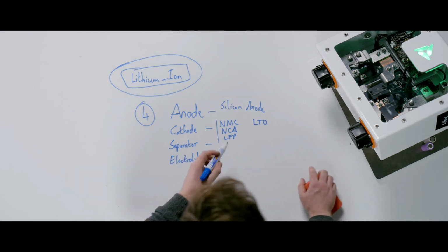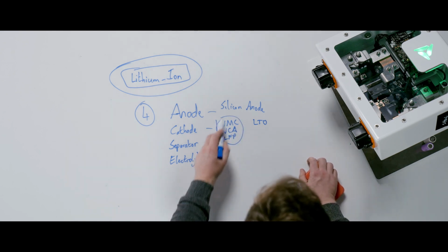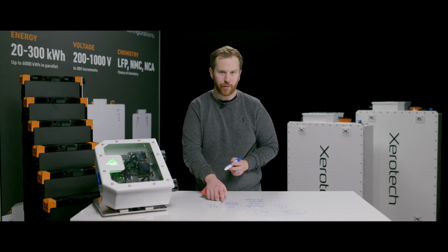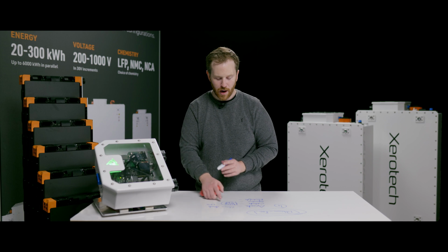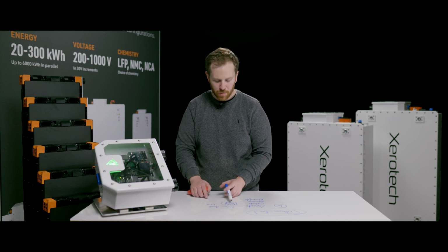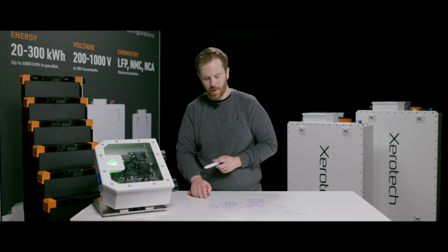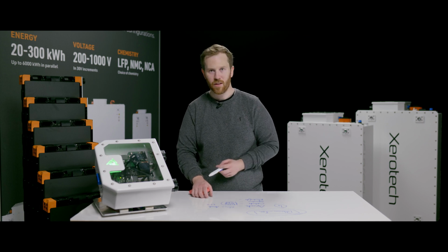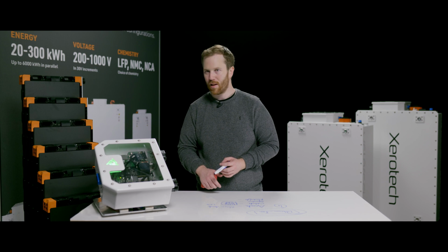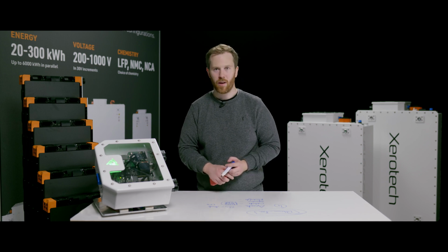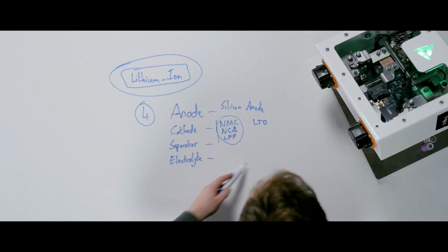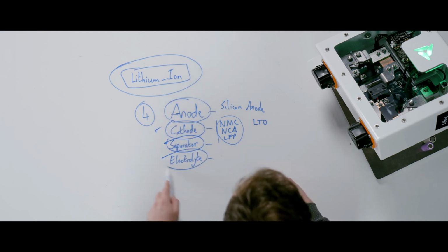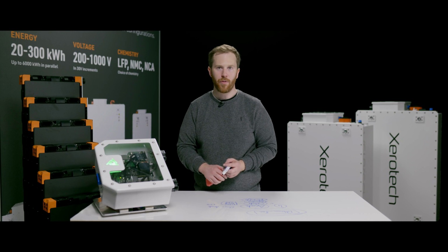The reason you've got to be careful with these and trying to say that, oh, it's an NMC or an NCA cell, is modern cell developments are starting to blur the lines between the two. So there's batteries that are NMCA batteries, there's LFMP, there's LFMP with silicon anodes, there's different inorganic electrolytes, there's ceramic separators. This is like baking a cake. When you change any one of these things, or in combination, you change the performance of the battery.